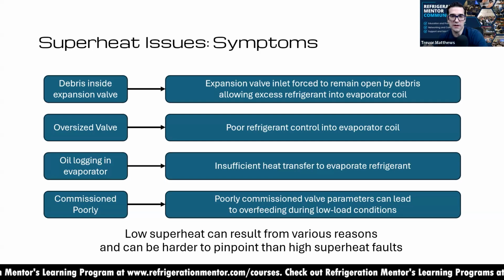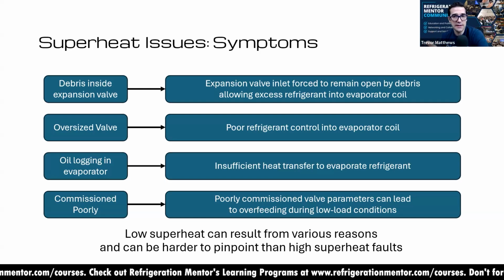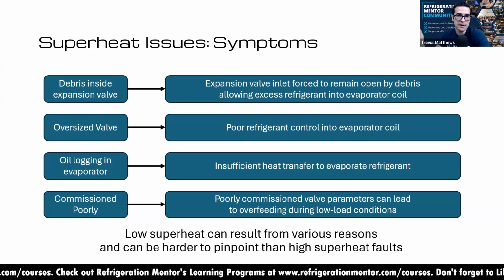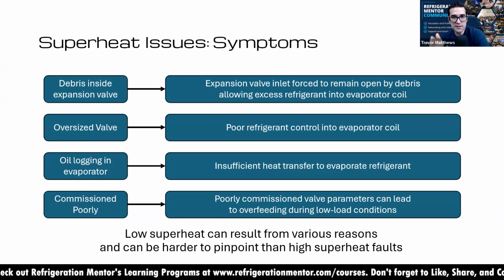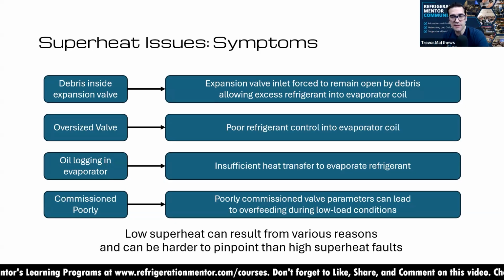Yeah, and I totally love looking at the trend graph. So if you're getting into CO2 and you're starting to see more case controllers, I highly recommend learning how to read the trend graphs, because it does take a little bit to work out which one I should use and which one I should be watching and monitoring. But for sure, when you're watching the defrost, when it goes into defrost, out of defrost, into defrost, out of defrost, you will see these consistent things happen as long as it's fine tuned.